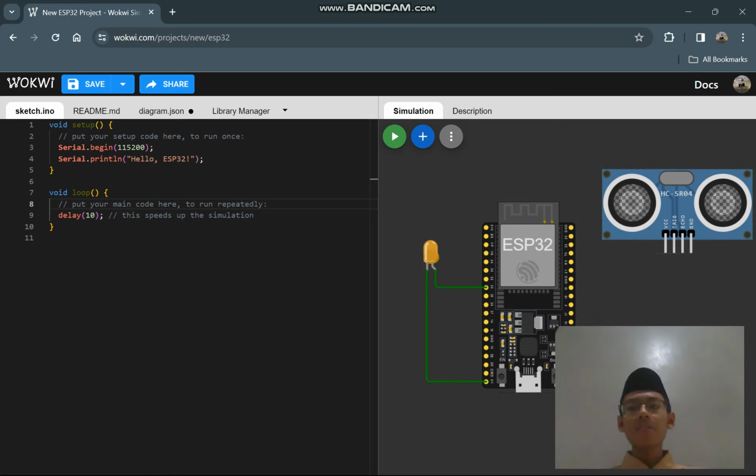So actually, before I continue, there are 4 pins here, or 4 connectors. First is VCC. So what is VCC? VCC is basically 5 volt in the ESP32 board. So it's used for receiving power, or giving power. Like the plus on the battery. Like in the battery you'll find a plus and a minus side, and the plus is VCC or 5 volts and the minus is ground. So you can connect this to